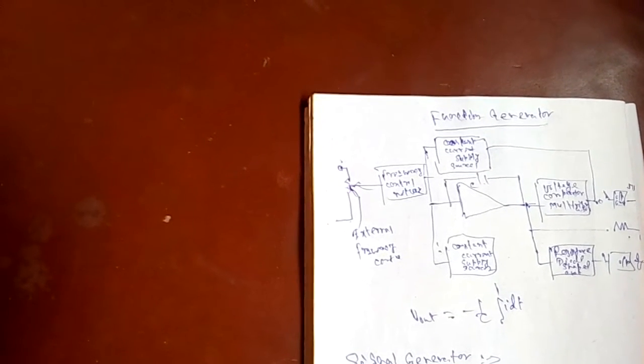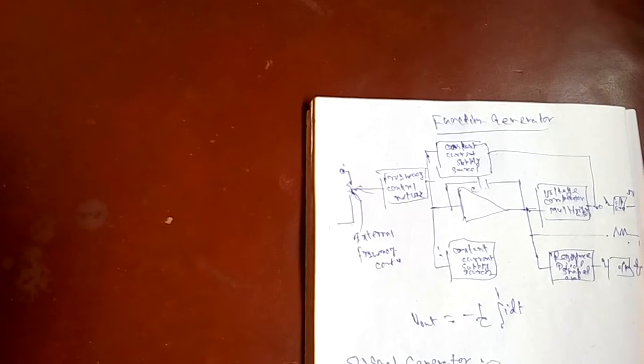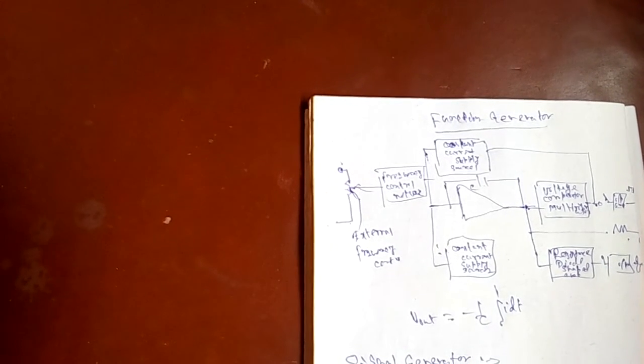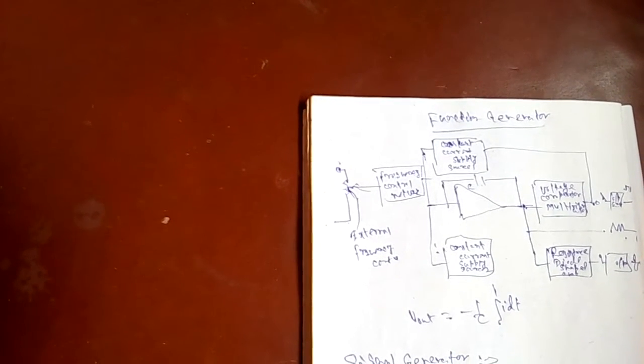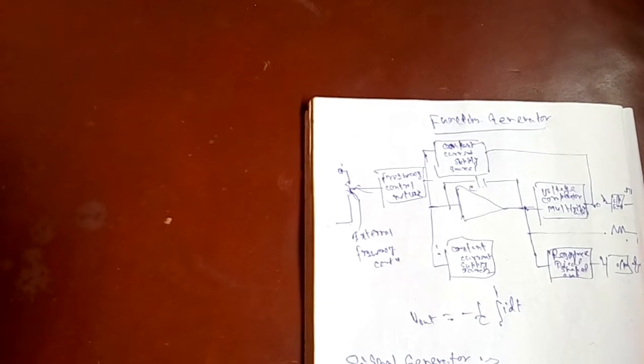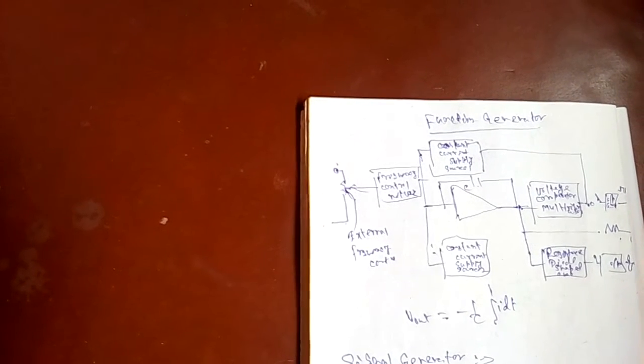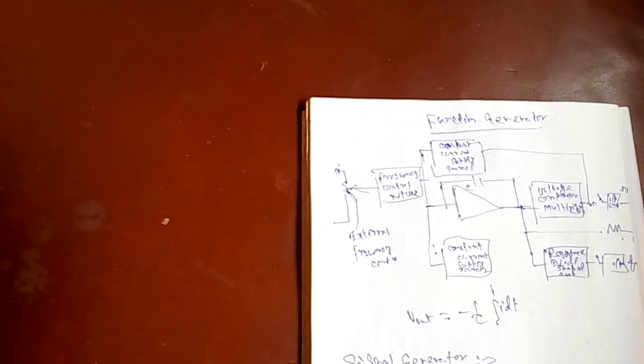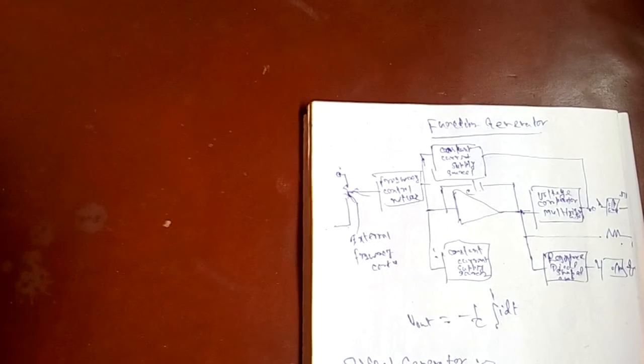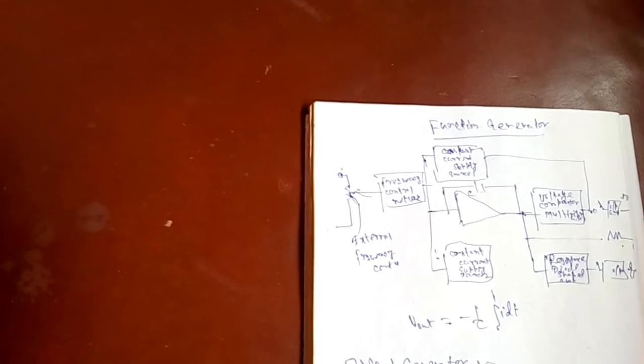They are often employed as a power source for the measurement of gain, bandwidth, SNR, meaning signal to noise ratio, standing wave ratio, meaning SWR, and other properties of the circuit. They are also employed for measurement of characteristics of antennas and transmission lines.